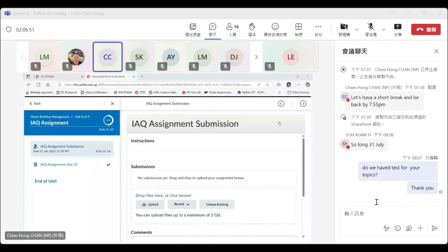Just like what you mentioned, if they have a lot of windows but these are all closed, then effective cross ventilation will not occur, and therefore the smoke, the gases that are being released are actually being trapped in a part of the building, cannot get out.